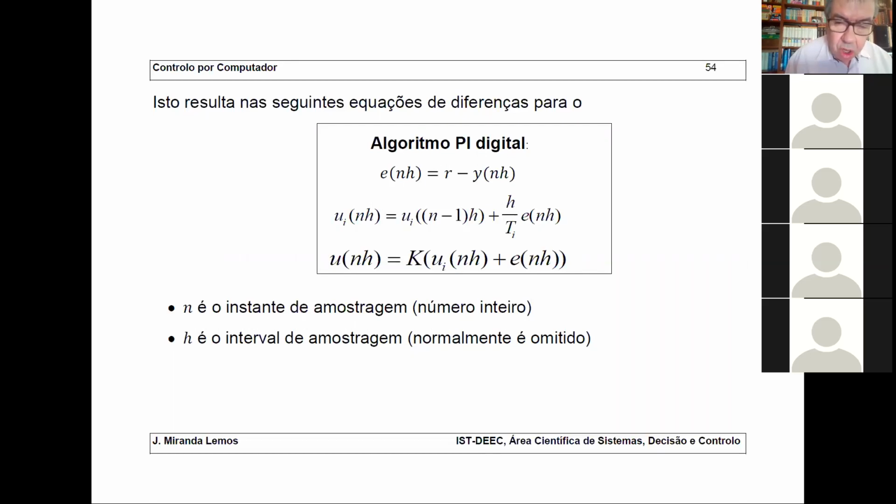Now, we used a controller that had more complexity. So instead of having just one position of memory in the past, we had more positions. Of course, the algorithm is a little bit different from this one, but we were having more memories of the plant variables in the past. Actually much more, say 4 or 5 positions in the past, and we could improve the result, the error, by a factor of 3.5.